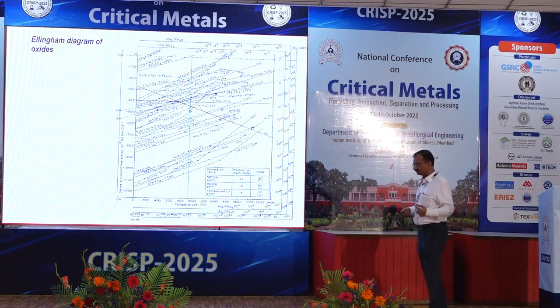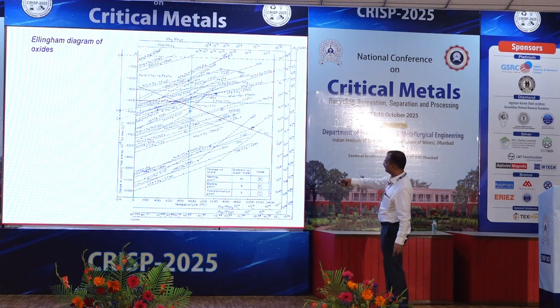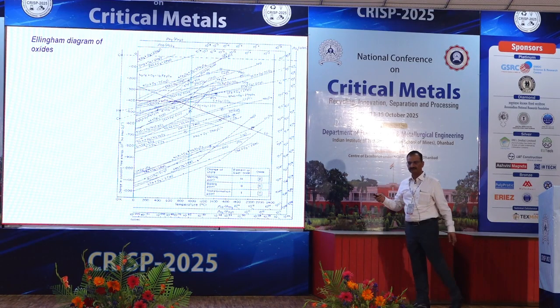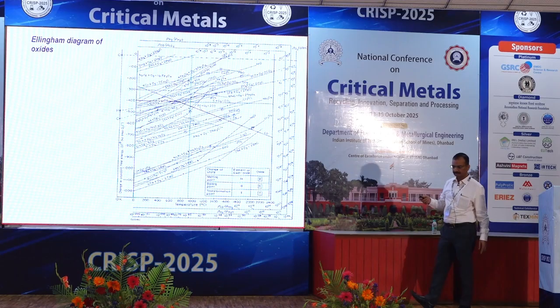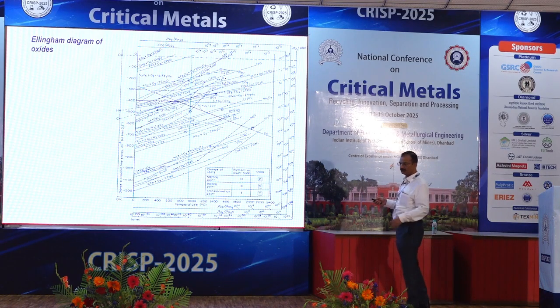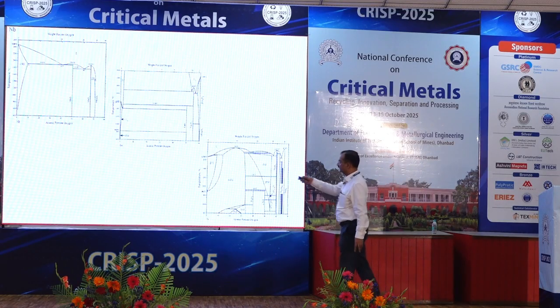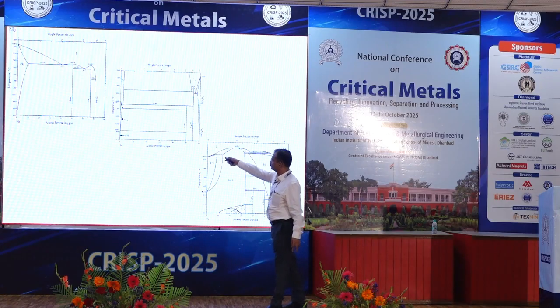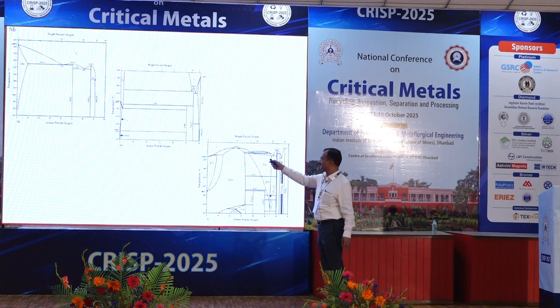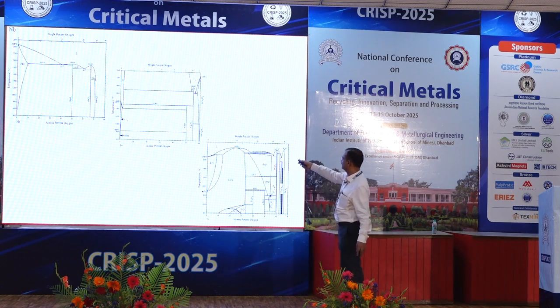Scientists are here from CSIR laboratories and research scholars, so please note that the Ellingham diagram is a very primitive way of dealing with extractive metallurgy, particularly of less common metals. It doesn't happen that you just reduce the niobium pentoxide and it will become niobium. It has to follow the phase diagram. From Nb2O5 it becomes NbO2, then NbO, and then Nb.